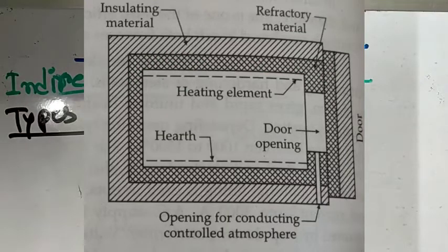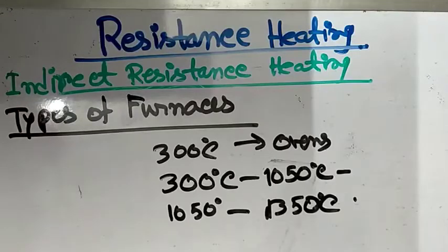Now, resistance heating using a metallic resistor is widely used for a particular atmosphere, as shown by this figure. Resistance heating, usually with metallic resistors, is widely used for heat treatment, but the temperatures attainable with metallic resistors are not high enough for melting most non-ferrous metals and cast iron. Graphite can, however, be used at much higher temperatures.